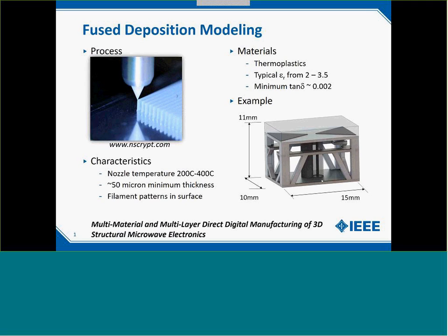Recently, there have been some custom materials developed using ceramic microparticles with thermoplastic material to form a composite, and dielectric constants in the range of 5 to 6 have been demonstrated, and up around dielectric constants of 10 using ceramic nanoparticles, having the low loss tangent values.